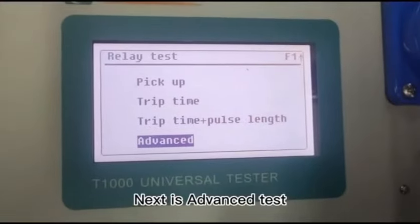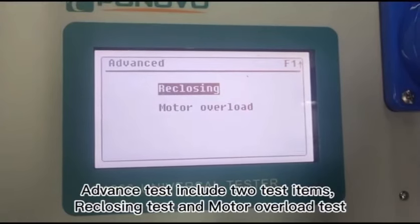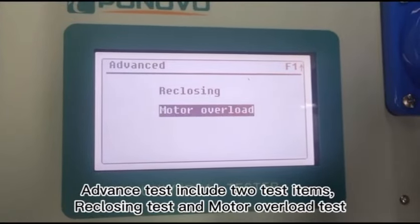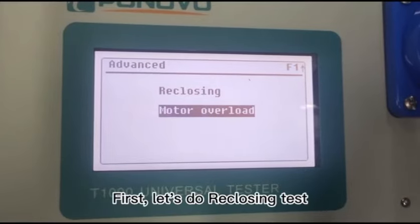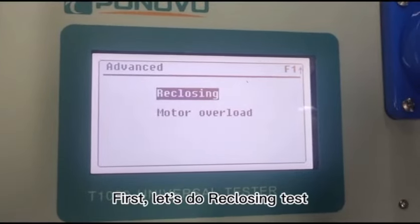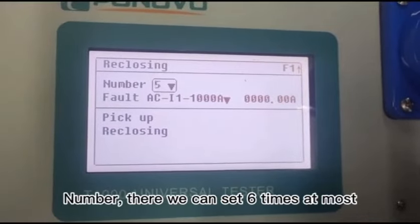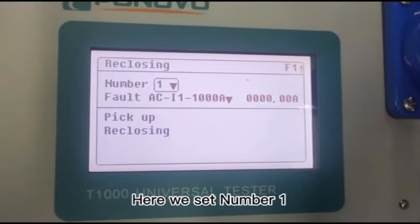Next is Advanced Test. Advanced Test includes 2 test items, reclosing test and motor overload test. First, let's do reclosing test. Number, there we can set 6 times at most. Here we set number 1.